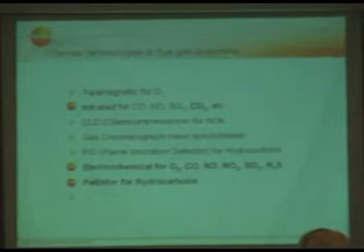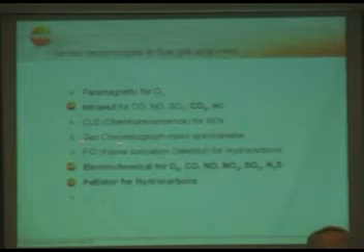Then we have also CLD, chemiluminescence, for NOx. This is basically an NO measurement, and they convert the NO2 back to NO, and then in sum you will get the NOx reading. Then we have gas chromatographs, mass spectrometers to measure all kinds of different gases.